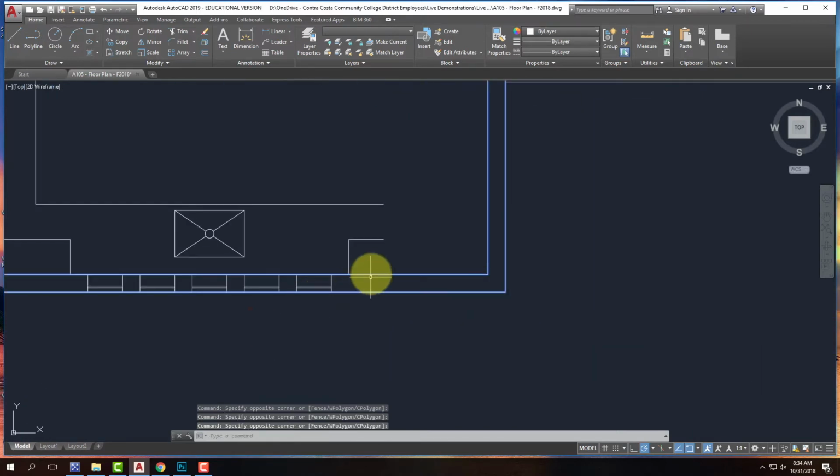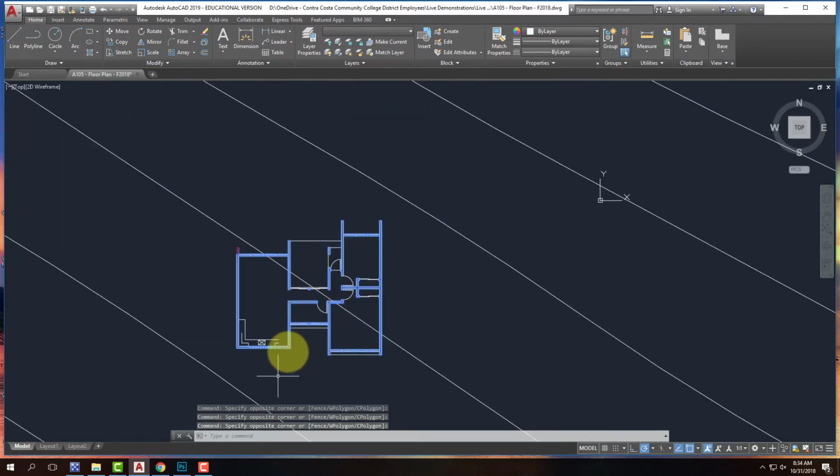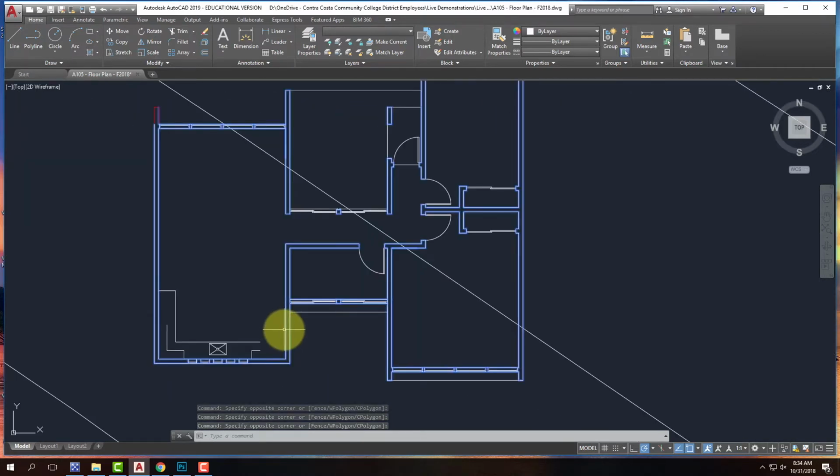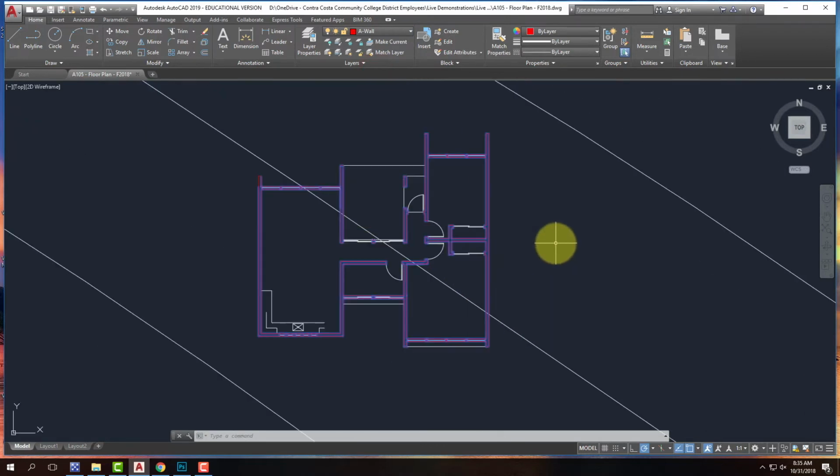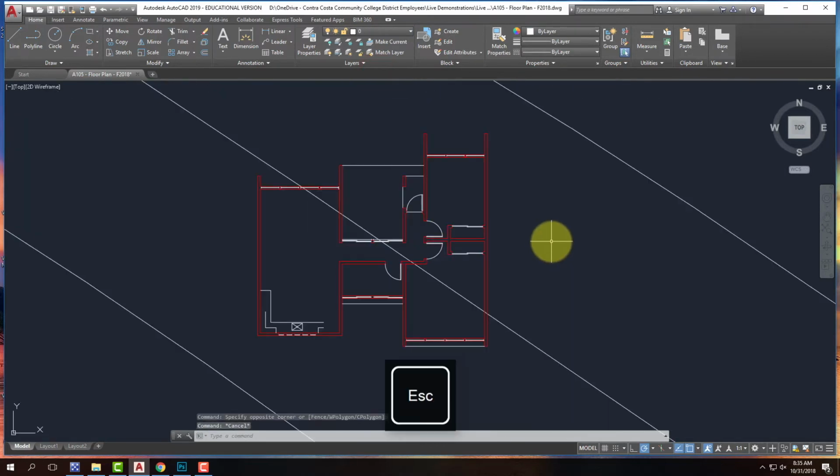And almost there. Perfect. I've selected all the walls. And once I have all those walls selected, I'll come up to my layers here from the drop down, I'll switch to wall, and we can see them all change to red, which is the easy way of saying, yes, I did end up selecting them all. That's good. That's a good sign.